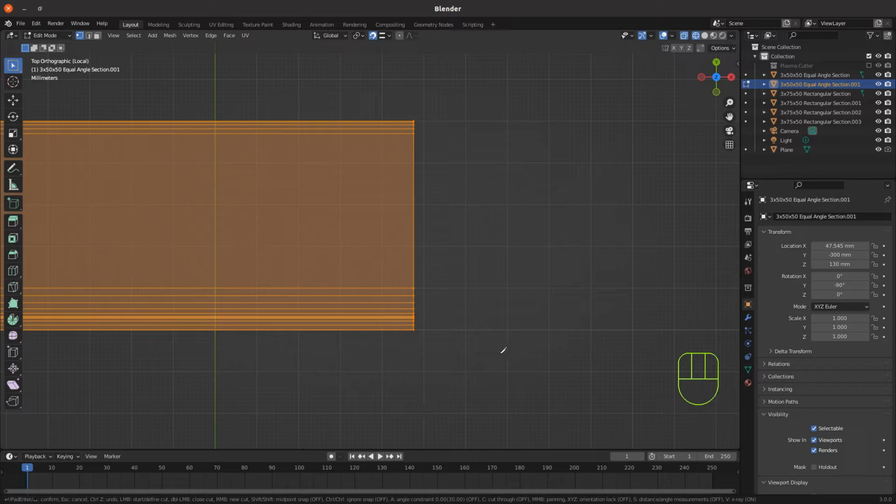So what I'm going to do is just snap the knife to the bottommost vertex on the right hand edge, and as you go over there you'll see the snap point show as a green square, and it'll stick to the bottom corner until you move the mouse a bit further, and then it just comes along the edge. But you'll see it just in this area close to that vertex it sticks.